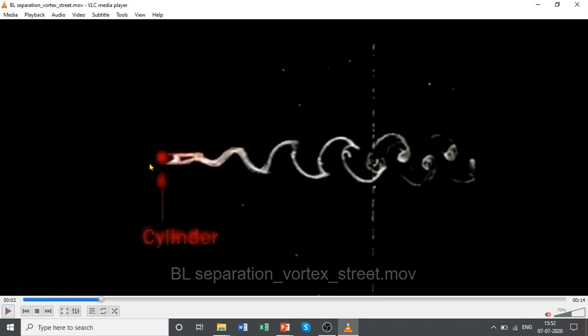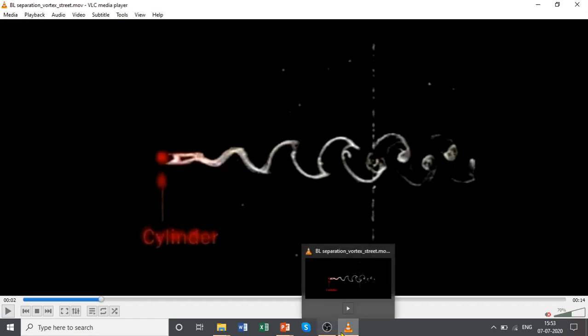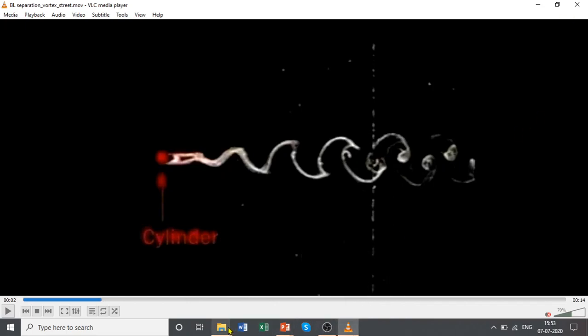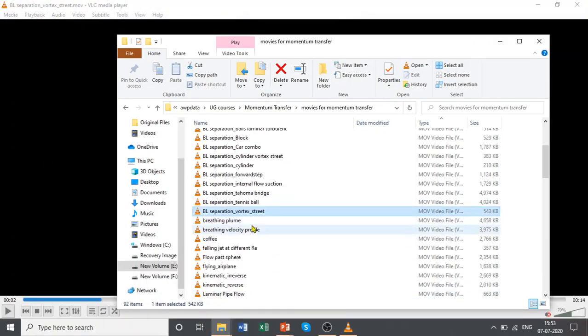So you can see, suppose I put this inside that vortex flow meter, and flow is going from left to right. These vortices form, and these vortices go along for so long. Now if I put something in this flow, it will alternately get hit by this vortex, this vortex, this vortex, and so on and so forth. So the flap, if I put it here, will just vibrate depending on when these vortices pass. And we measure the frequency of that flapping, and we would be able to calculate the flow rate going through this.